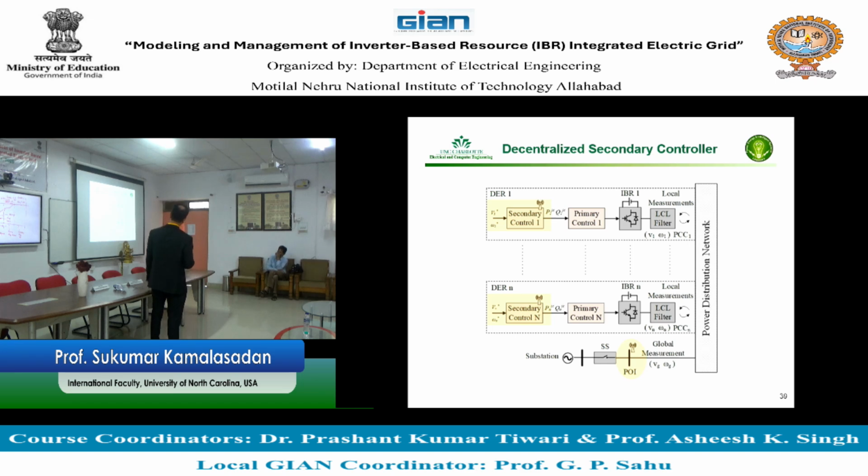So this inverter, what you see right here, the control that controls the inverter is one DER's primary control, right? If you have many of them in an electric distribution network, for example, you will need the secondary control to maintain the voltage and the frequency, right? Remember the voltage and the angle that is generated from the inverter. Where is the inverter looking at that voltage? On the point of common coupling. Can the inverter receive voltage from the substation or some other place? No. Is it the job of the inverter controller to see somewhere else?